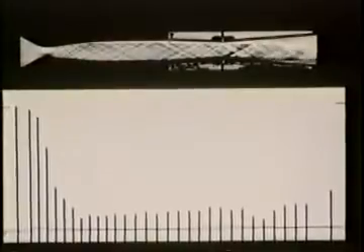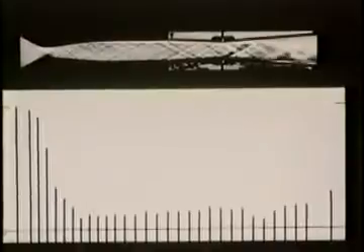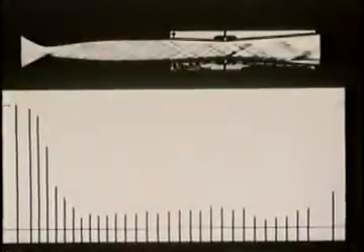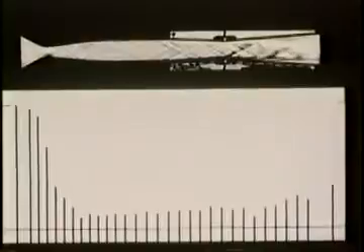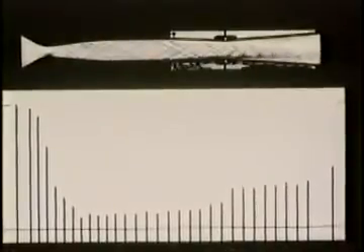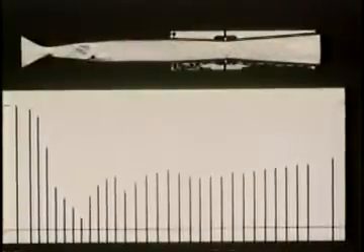If we now close the control valve slowly, we drive the shock pattern upstream toward the second throat, where the Mach number is lower than the test section value because of the supersonic compression. By increasing the back pressure sufficiently, we can unstart the channel, or disgorge the shock wave. And we can restart by again opening the valve.